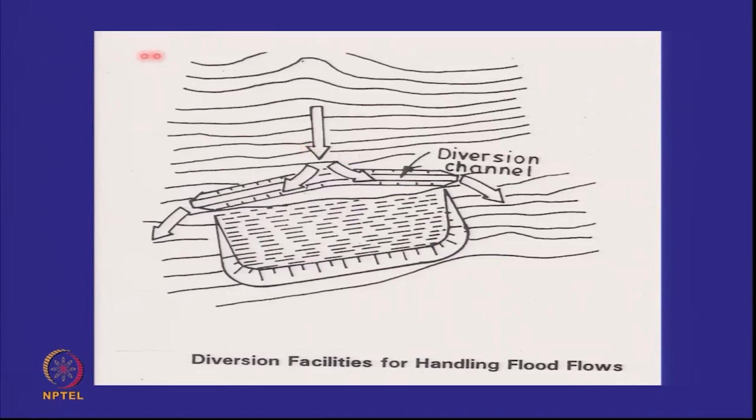And this is the concept of the diversion channel or the interceptor drain. If you are on a side slope landfill, please catch the water and divert it from the sides. Don't let it enter the landfill.